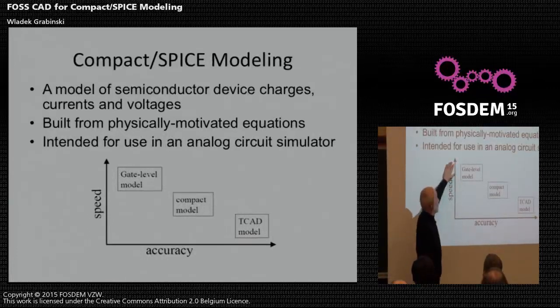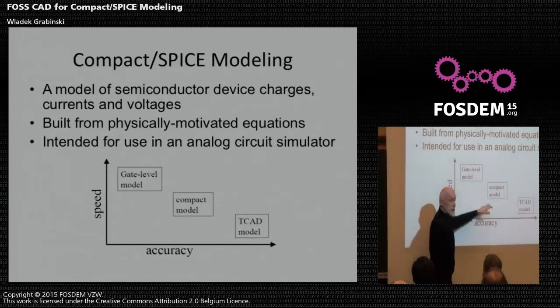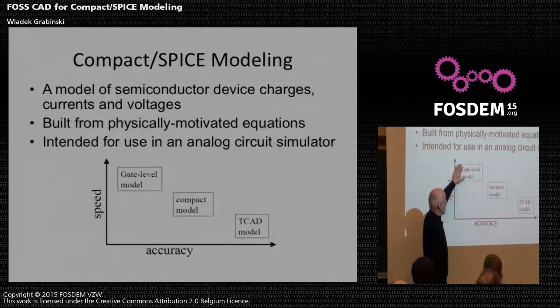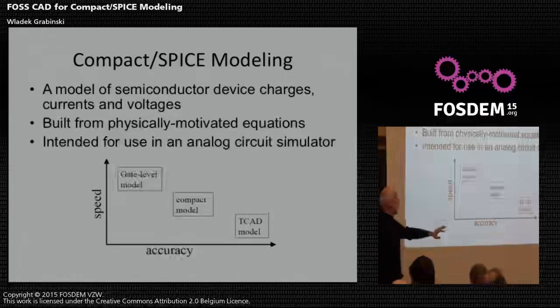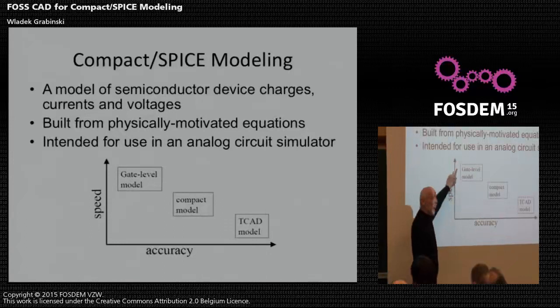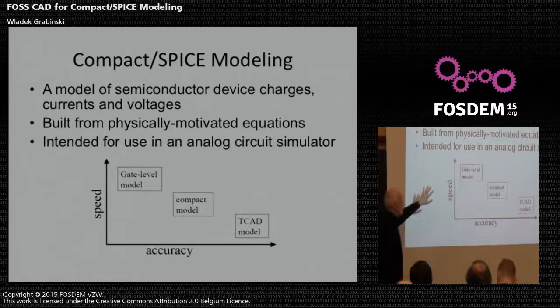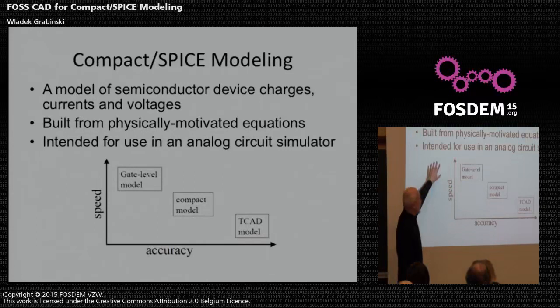So you go to transistor level, but you need compact models to create, for example, timing libraries to run digital simulation. We are not covering this topic here, and I guess both tools, Quarks and ngSpice, are not on this level, but they allow behavioral simulation of Verilog digital blocks or VHDL digital blocks. So we have FOSS tools also for this level. It's huge circuits and very fast simulation.